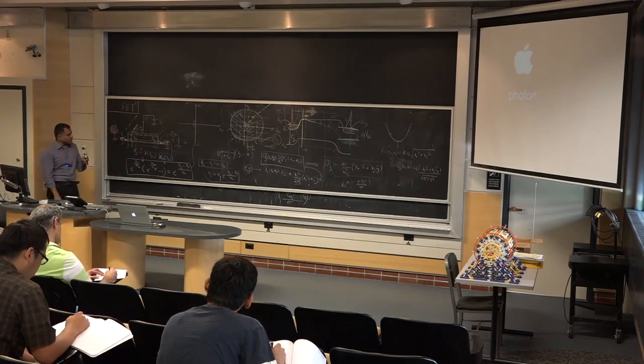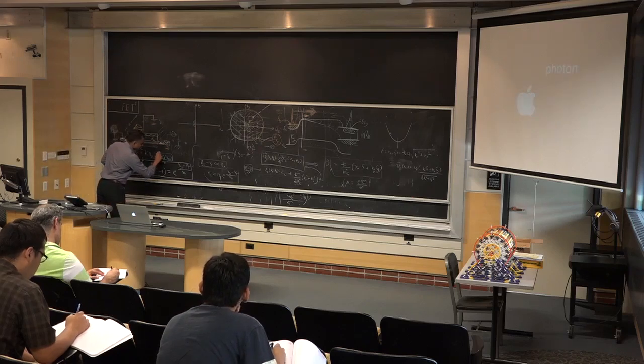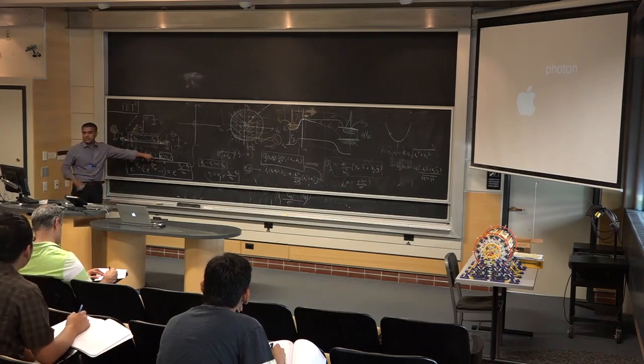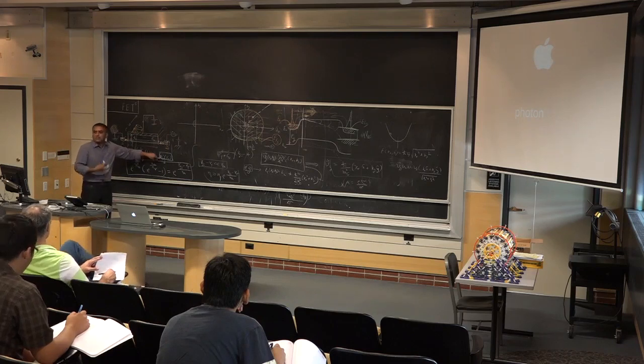So what does that mean? It means if the gate says this is your carrier density, no matter how much source or drain voltage I apply, this is always the carrier density at that point. So it is in complete control. This happens only in a very well-designed transistor. If you don't have it, it's not a good transistor. Because this is the heart of gain.